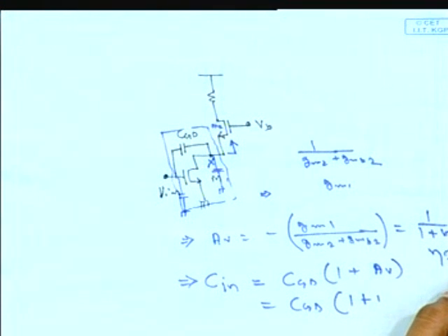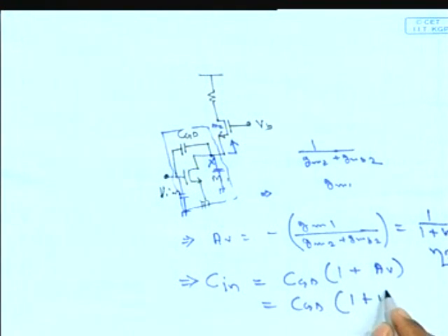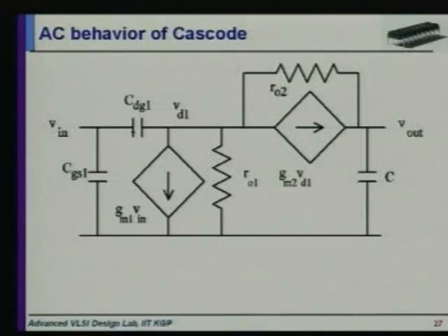It may be approximately equal to 0.2 in our CMOS technology, so we can neglect that. So Cin is nothing but 2 CGD, but in the case of the common source stage we get a very high gain, that is gm RD. So this type of Miller capacitor effect is mitigated here. Okay, now thank you very much.